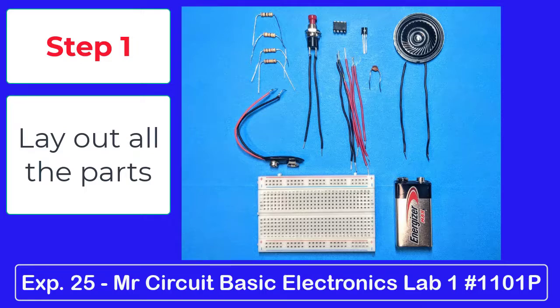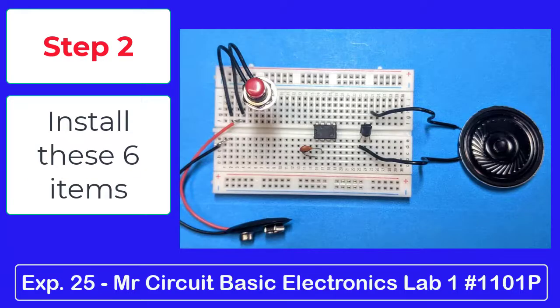Here are the steps we suggest you use to construct the circuit on your breadboard. Step 1. Lay out all the parts needed for the circuit. There are a total of 16 items counting the jumper wires. Step 2. Install these 6 items: the battery snap, the push-button switch, the disc capacitor, the 555 timer IC, the NPN transistor, and the speaker.